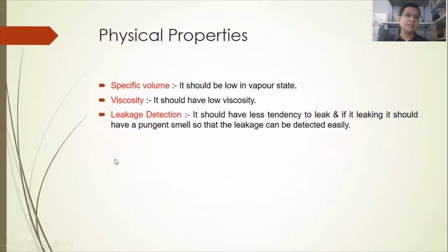And then physical, only three parameters should be measured. Specific volume should be low in vapor state, viscosity should be low, and leakage detection. It should have less tendency to leak, and if it leaks, it should have a pungent smell so that leakage can be detected easily. It should fulfill all these items.